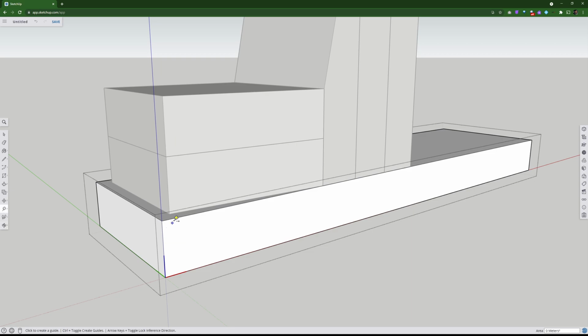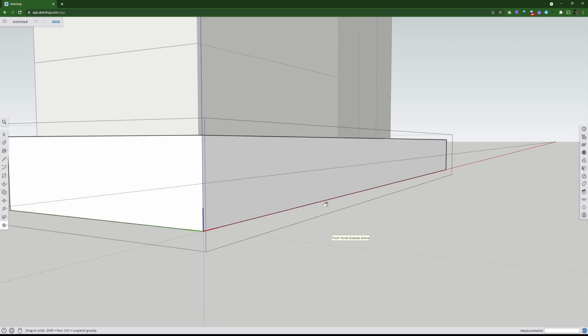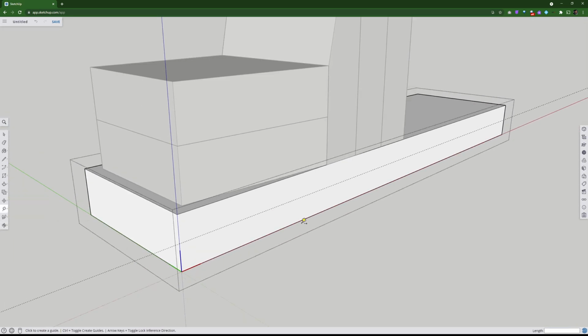The first one we're going to do is going to come down from the bottom and find the midpoint. It's telling me 10, but it's just rounding up because we know it's really 9.5. Half of 19 is 9.5. But I've got a blue dot there, which means it's a midpoint. So that's where I'm going to put a line. I would run that with the marking gauge in the workshop. I would find the midpoint and I would run my marking gauge along there, be a light line. Okay. I want to come in from both ends and drill a hole.